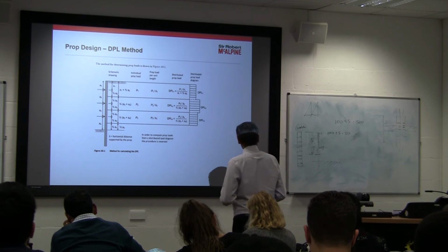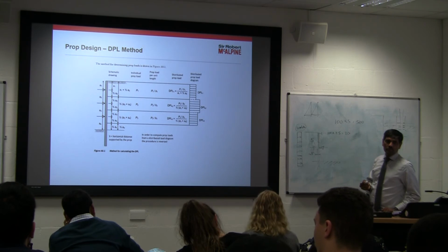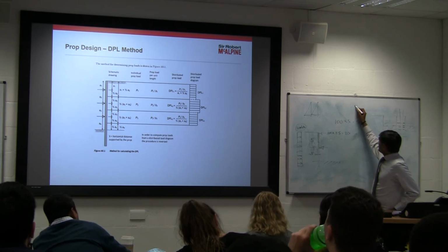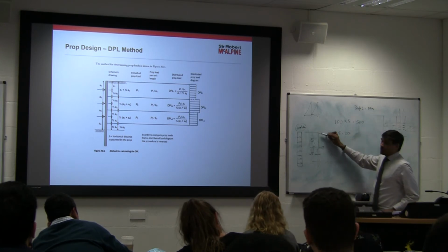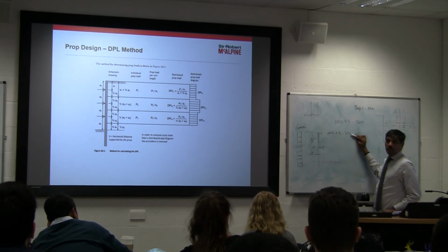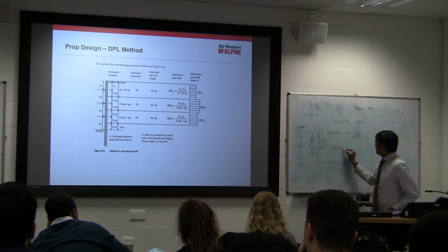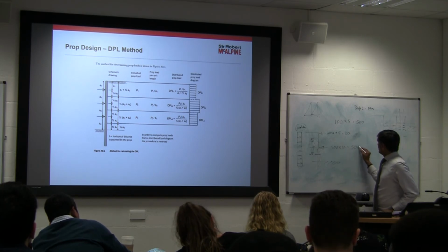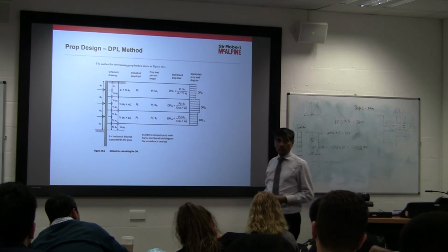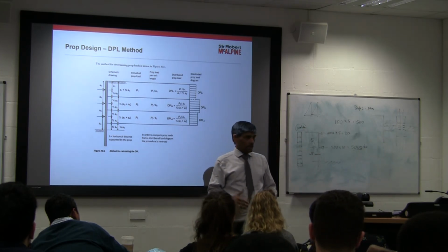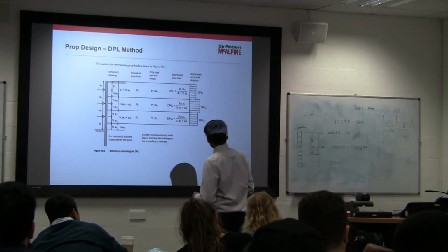Yeah? So this method tells you, if my props are spaced at 10 meters, let us say prop spacing is 10 meters, then my total force on each prop will be times 10, right? Here it will be 500 times 10. So we're talking about 5,000 kilonewtons, 500 tons of load on the prop. That raking props, that fly-through props, whatever we talked about, is roughly about 500 tons. That's a sort of order of magnitude.